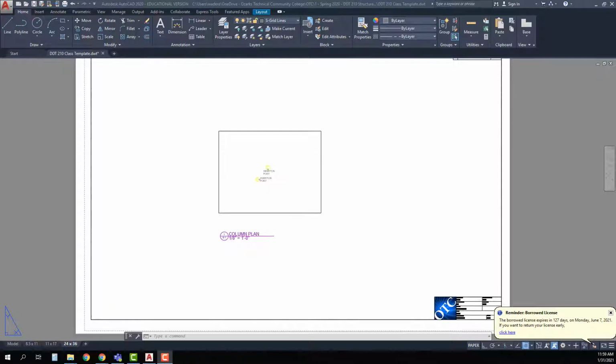Then I see a note that says see chart on page 139 of the textbook, and we are going to use 20 PSF/LL. So if I go to that chart and I look on the left, I'll see 20 PSF/LL, and on the right I'll see 30 PSF/LL. Then I will see width and height, B, C, and E for each one of those. We said we're using the 20 PSF, so if I go down that side of the chart until I find 30 feet, then that's going to give me the information.